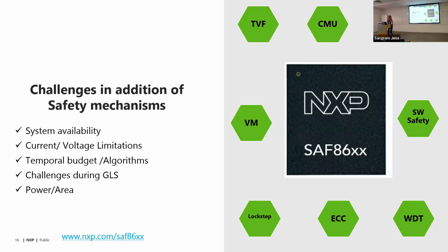One of the other challenges is that during gate level simulations, it is a real pain to test all these self-testing scenarios, because it is not just running one particular partition, it is multiple partitions running in parallel. So the run times are also very critical here. On one hand, you have all kinds of safety mechanisms, but making sure that they work properly, that they adhere to all the architectural specifications that you have, and that you are fulfilling the customer's criteria, actually becomes a challenge.